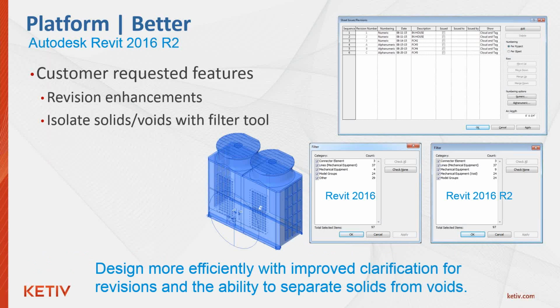All right, revision enhancements. Additional information is now available for revisions to make it easier for you to see exactly how the revision number will be generated and to select the revisions to be included in your revision schedule. The sheet issues/revisions dialog box now has a new column for revision number. When numbering is set to per project, this column will display the actual revision number that will be generated based on the sequence, numbering scheme, and numbering options. This column does not display if numbering is set to per sheet. It has to be set per project.